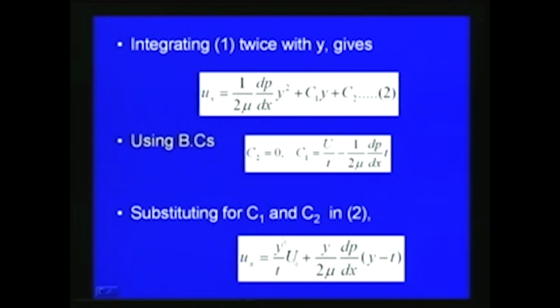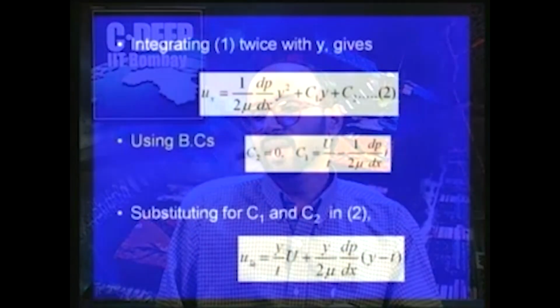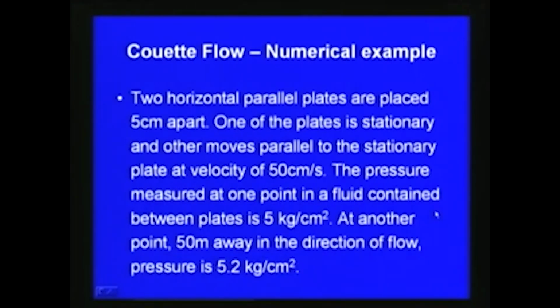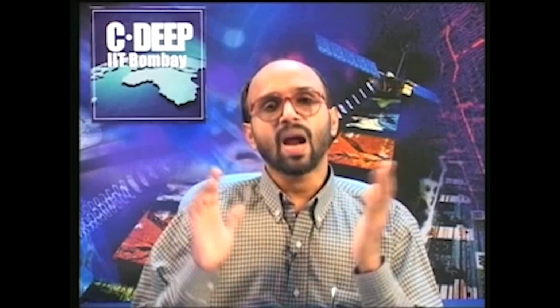And then if we want to find out the flow between these two parallel plates, then we can integrate between 0 to t of this velocity. So, the velocity into area will give the discharge passing, so we can integrate between these two to get an expression for the discharge passing between these two plates. So, like that various parameters can be found out. This is called a Couette-type flow, which has got a number of practical applications in various engineering problems.